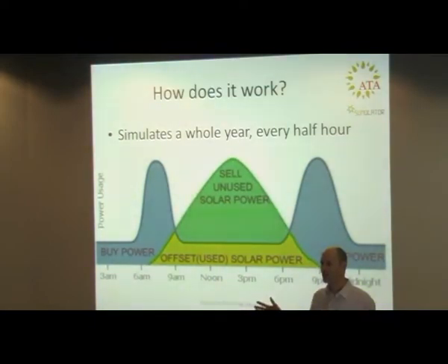You don't just average all of your 1st of Januaries, because then you miss the variability. Instead, you take each month in turn. Let's look at January. You go to January 98, and January 2000, 2001, 2002. You do some stats on each of those Januaries and see what the total or average sunshine was. The one which was closest to the average is the January that you pick for your typical year. Then you look at February and do the same thing. Your January might come from January 98, and your February from February 2011, March might come from March 2000, whichever were the most typical, and you splice them all together to make a typical year. We did that for each location that you can pick.